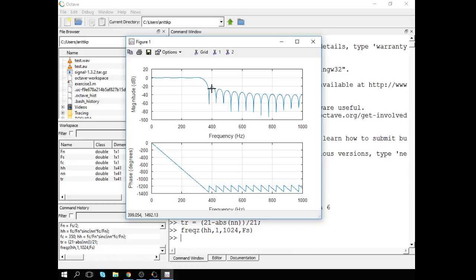Excellent. How to improve it more? Use a real window, not triangular. The only good part of the triangular window is that it's fast to calculate even on a small processor. But on the other hand, you usually know the width of the window by selecting it. So even for small processors, you can always have a constant lookup table for the coefficients.